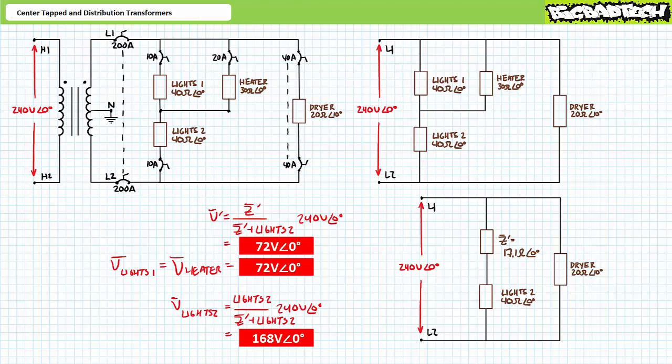It is for this reason one might observe odd behavior in a system lacking a neutral connection, such as unsteady lights flickering and dimming, or crazy motors surging and dying as loads are connected and disconnected. If you've ever had the misfortune of working on a house formerly owned by tweakers as I have, be aware that those fixtures that they haven't stripped and sold for scrap metal most likely don't function as intended because they're not connected as intended. Again, not only does the neutral line in a split-phase system carry imbalance current in the event of load imbalance between phases, it also serves to ensure single-phase loads have access to a fixed potential.